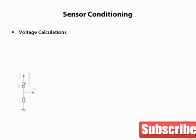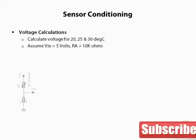Let's calculate the output voltage of our temperature sensing circuit for temperatures of 20 degrees C, 25 degrees C, and 30 degrees C. We'll assume that our process can accept a 0 to 5 volt signal, and we'll select Ra equal to 10k ohms. Using our equation, V out equals Vn times Ra over Ra plus Rb.